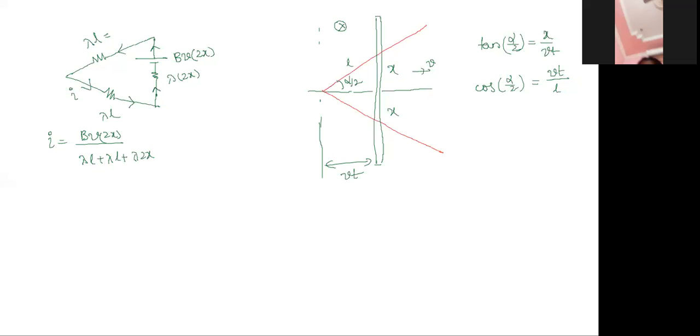Let me go through it once again. So the rod rotates here. As the rod rotates, EMF is induced here. Due to EMF, there will be a current. Due to current, there will be a torque. Due to torque, the rod will have some angular acceleration, so omega would get affected. Now for that not to happen, I want to connect a source E such that a current flows, and this EMF has to be such that the net torque on the rod is zero, so that it moves with a constant angular velocity omega.